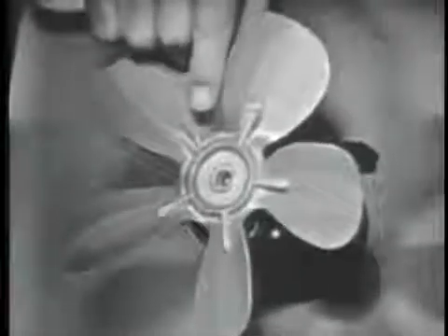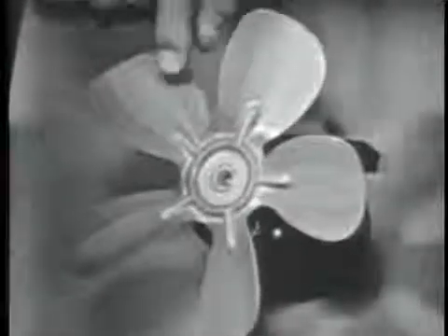Very good. Now, when we put this fan blade on the rotor, we have increased the load or the drag on the motor. And therefore, it's going to turn a little slower. In fact, I've got to give her a little start there to get it going. Now, it turns slower. Before, the rotor was turning almost as fast as the magnetic field, under a no-load condition, of course. Now it slows down a little. Well, it slows down a lot because it's got work to do. There's more drag on it. Right. That's the way.